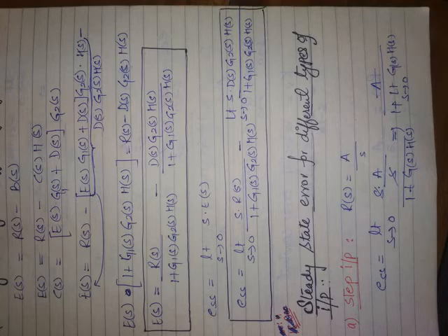Now listen here. What is this output compensation? You see, normally controllers or compensators are placed in the forward path. But if this controller or compensator is placed in the feedback path like this, that is also one of the configurations.